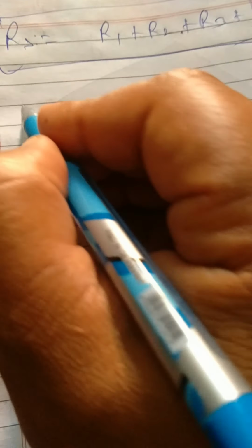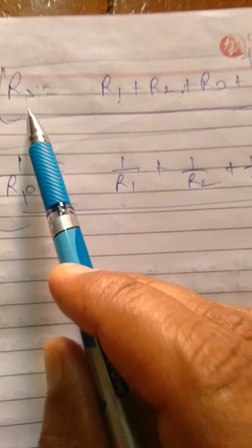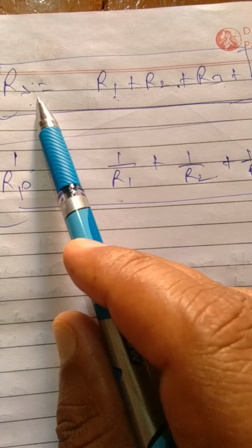You have to learn the series combination result. Let us suppose here we are taking the example of three resistors. This is the series combination result: RS equals R1 plus R2 plus R3, and there can be more up to Rn. And in parallel, this is RP: 1 by R1 plus 1 by R2 plus 1 by R3 plus up to 1 by Rn. There are n number of resistances, but in this chapter, your 10th class, they are taking the examples of only three resistors, and by proving these expressions, these are correct expressions of series R1, R2